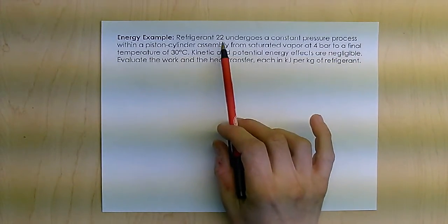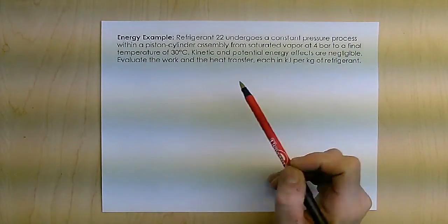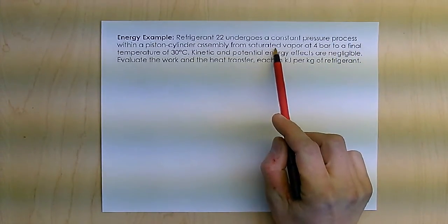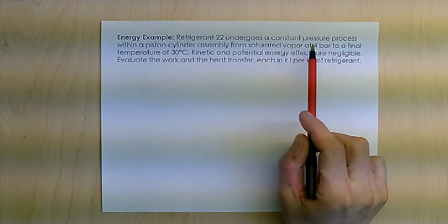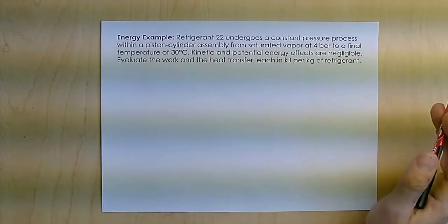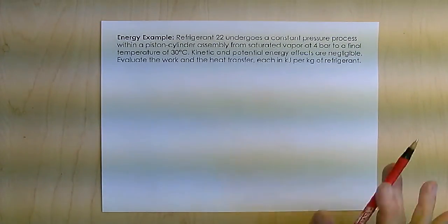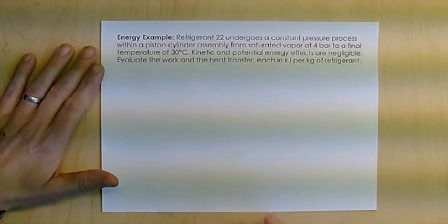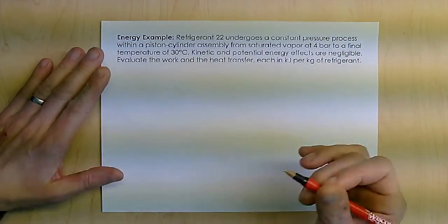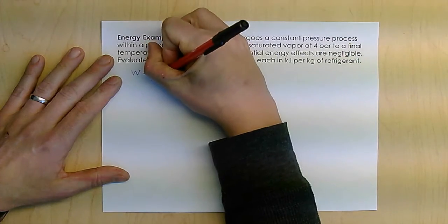In this problem, we have refrigerant 22 that undergoes a constant pressure process within a piston cylinder assembly from a saturated vapor at 4 bar to a temperature of 30 degrees. As per usual, we're going to neglect kinetic and potential energy, and I want to find the work and the heat transfer of this process. So, as we know, the work of a process is the integral of P